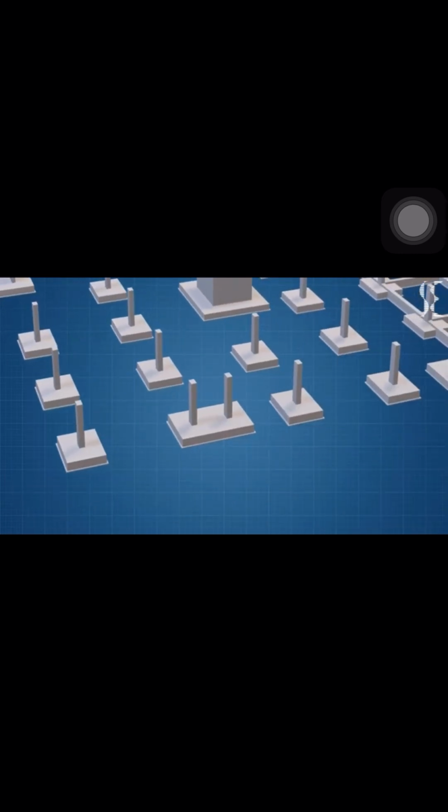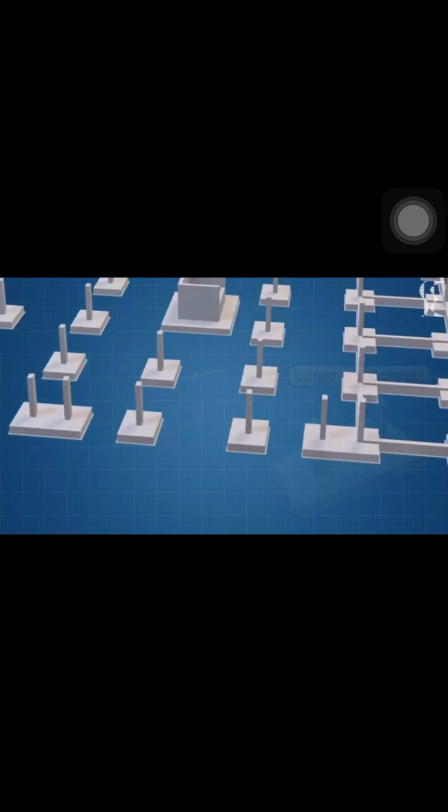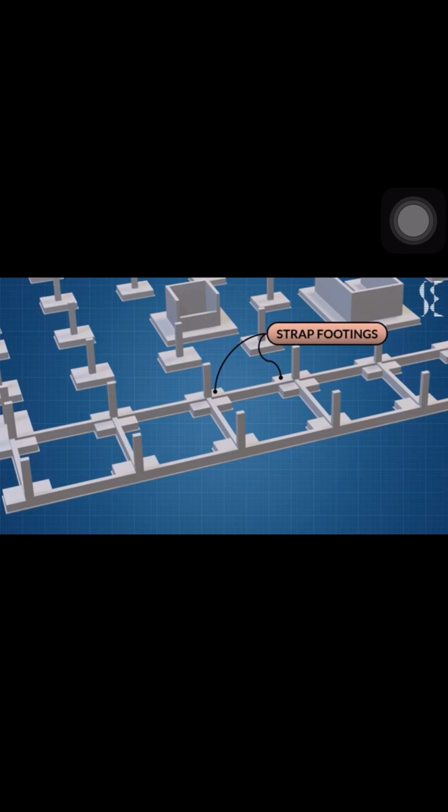In shallow foundation, they are often placed like a meter or 1.5 meters deep to distribute a building weight to the soil. In those shallow foundations, we normally use isolated footings, a common shallow type that supports individual columns and ensures stable weight distribution, found mainly in residential and light commercial buildings. These are simple and cost-effective, sized based on columns load and soil capacity.